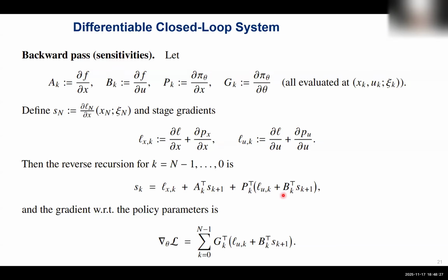And that's what is allowing you to compute these sensitivities that you can now aggregate for computing what you can consider your critic for training the policy. Now, taking the gradient of this loss function that is fully model-based, fully MPC inspired, in the direction of your policy parameters, you can have direct policy optimization in this way.